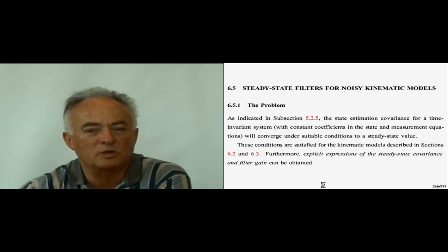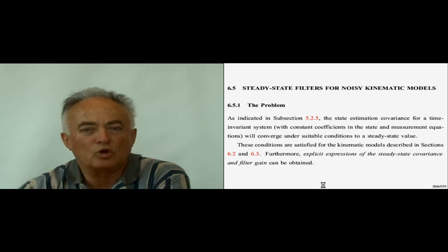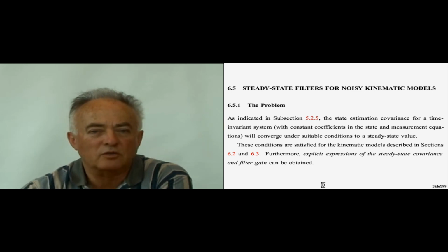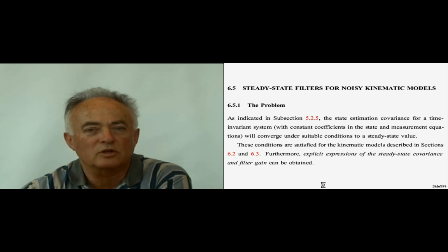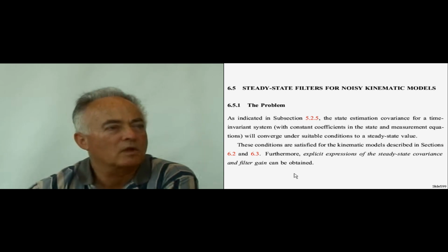It is enough to observe position for such states. Second, the process noise, as defined in both cases, ends up yielding the controllability condition satisfied. Therefore, the Riccati equation is yielding in steady state a unique positive definite solution.